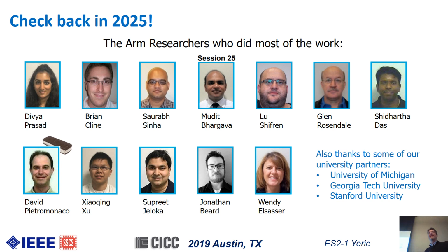What I didn't tell you is they put the world's largest heat sink on top of that thing. And that heat sink spread stuff out, and at the edge of the chip they had giant heat pipe TSVs all the way around the whole thing to get the heat back down to the package. And that was just the 2 layers, memory over logic. If you're talking about 2 logic layers, 4 logic layers, absolutely it's going to be a big problem.